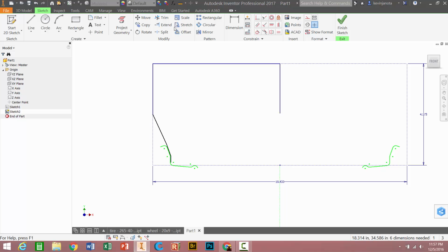Once you have that basic shape done, we're going to offset, bring it in 0.5, hit escape. What that does is that sets up our sidewall thickness. And I'm actually going to delete that and this line here. I'm going to draw a new line about here and over, escape, X to trim, escape, and dimension. And I'm hovering to wait because I want to make sure I select just the solid line, not the dotted line all the way across. We're going to make that 1 inch thick there.